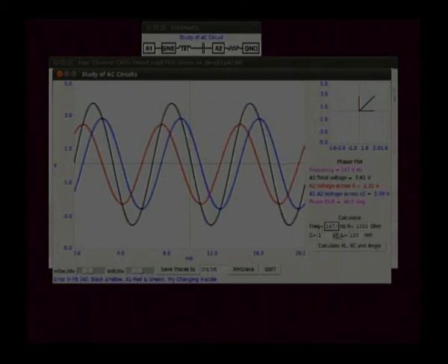147.4 hertz, and our resistance is 1 kilo ohm, but there is no inductor. So, make that 0 and calculate the values. So, you can see here the capacitive reactance is 1079.7 and there is no inductive element, and the calculated theoretical value of the phase shift is 47.2 degrees, and we are measuring here 48 degrees. So, what we have done now is only the capacitor and the resistor in the circuit.